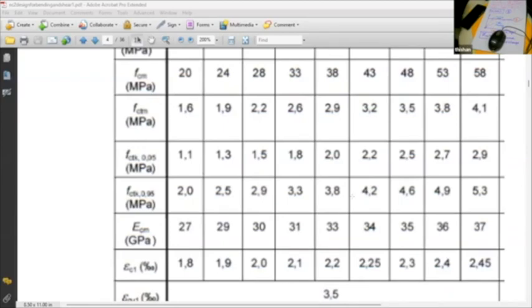And that is the time you need very good dynamic behavior with respect to wind-induced accelerations. At the beginning of the project, by the time you sell your apartments, if the building is stiffer, it will have a lesser wind-induced acceleration, and you will find people are happier, because your calculation was more based on a 1 year return period.